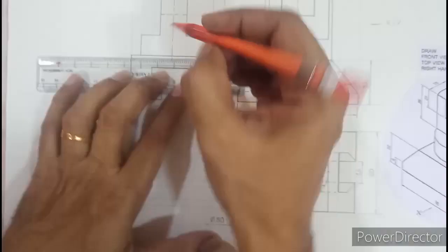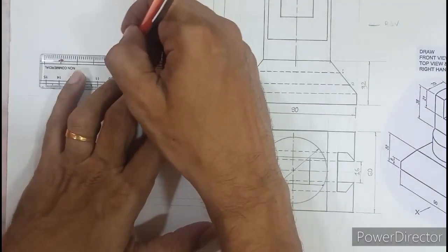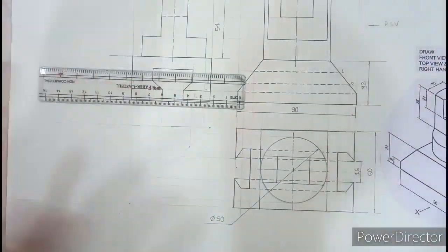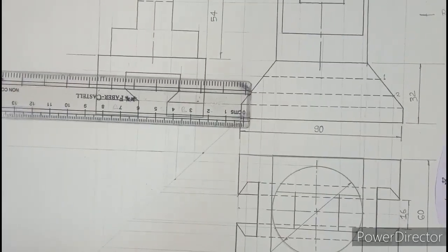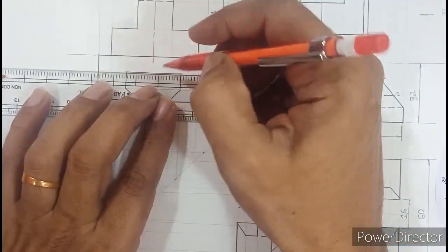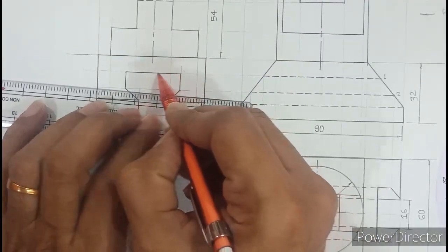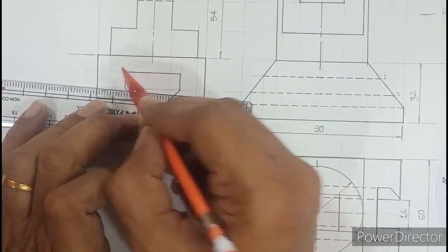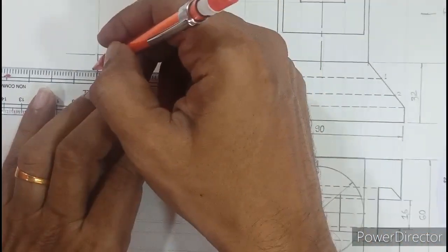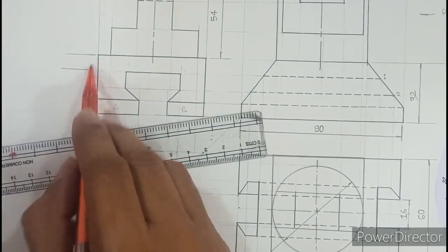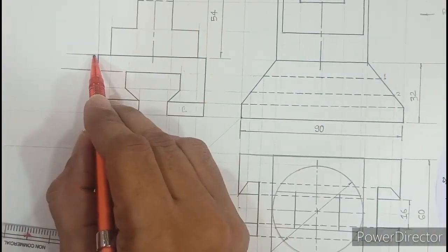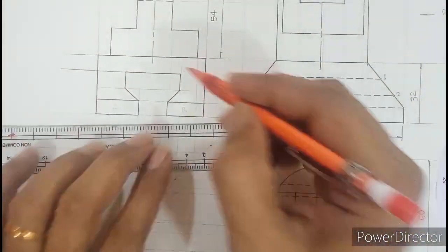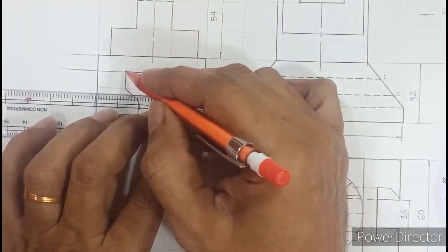So suppose if I want to show 9 on this side, the first extension line from here. Now, I will zoom a little. Now this height is 9. So the object line of 30 millimeter ends here. You can see that. So from here you have to leave a gap of 2 millimeter. Remember, don't leave gap from here. If you leave gap from here, you won't understand where this 9 is from where to where. And if the same gap is left from inside, now it is much more clear that 9 is from here till here. So always you have to leave 2 millimeter gap from where the object line ends.